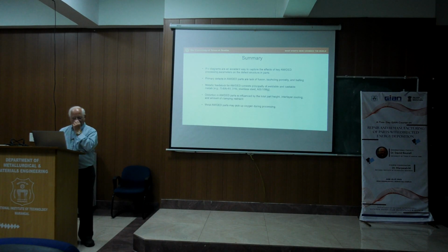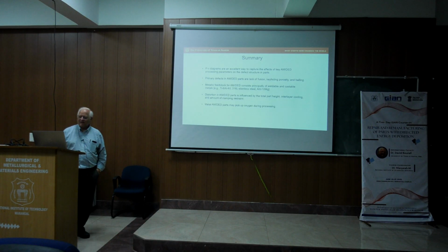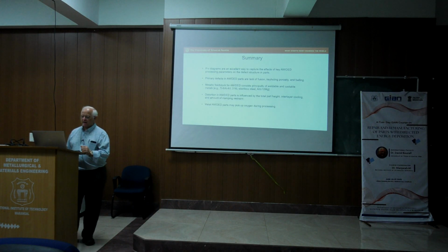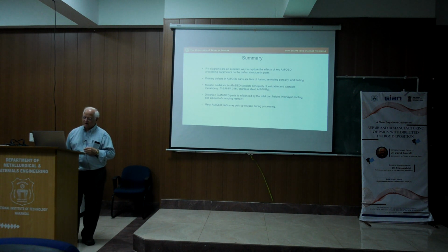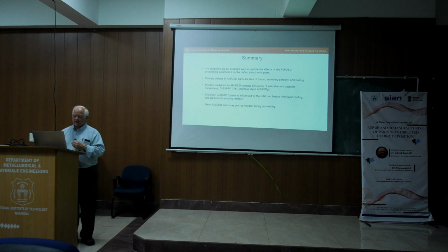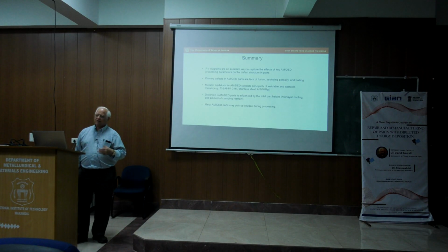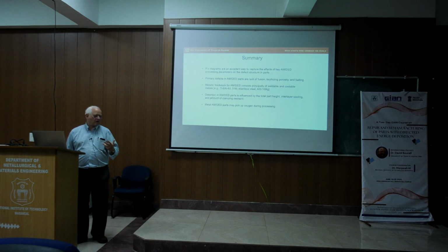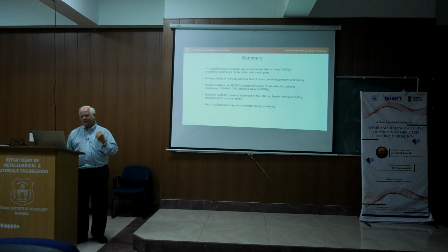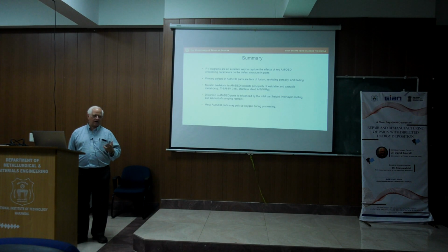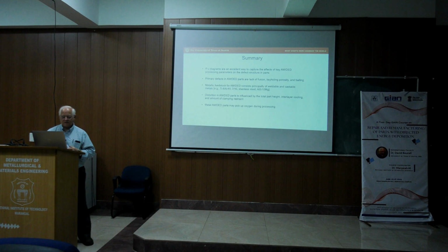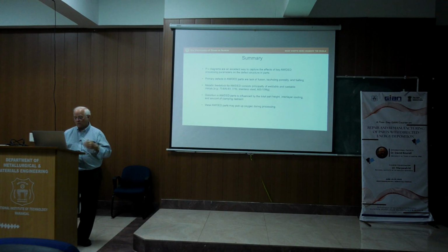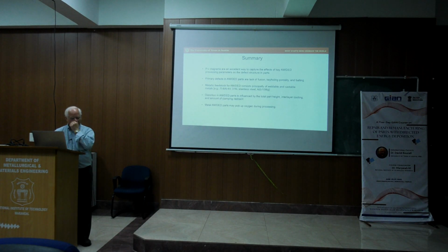But anyway, the third point: metallic feedstock for DED consists principally of rollable and castable metals. Again, if it's rollable and castable, it can typically be additively manufactured. And then I give the classic examples for the different systems. Cobalt chrome is a very castable material. The nickel alloys that we showed, the Inconels, the Monels, are all readily processable as well, and they appear very well in additive manufacturing.